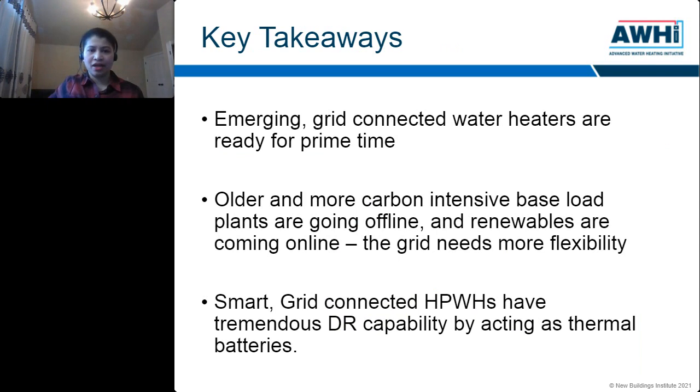So I would like to conclude by summarizing that emerging and grid-connected water heaters are ready for prime time. Carbon-intensive base plants are going offline, and distributed energy resources are coming online. So the grid requires more flexibility, and smart grid-connected heat pump water heaters have tremendous demand response capability to shift load to off-peak hours and act as thermal clean grid-connected batteries.